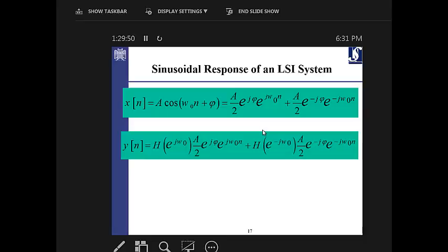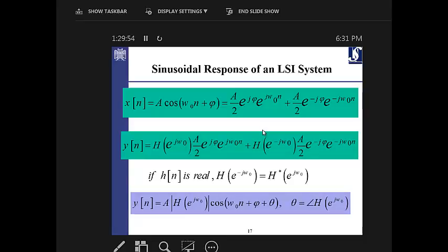And here is another example for a sinusoidal signal. If you have a signal like this, x of n, a cosine signal, periodic, then you can represent the signal as exponential terms. And if you have the exponential terms, then you see that e to the power of j something is nothing but the basis or the atom in the Fourier domain. So everything input as a superposition of this would be something as a coefficient of that. So here you see that we have a coefficient, a over 2, a half, which is a constant.